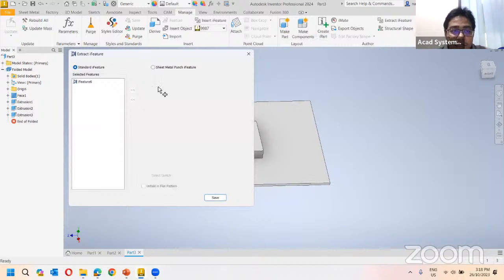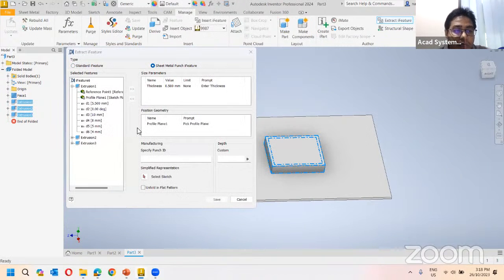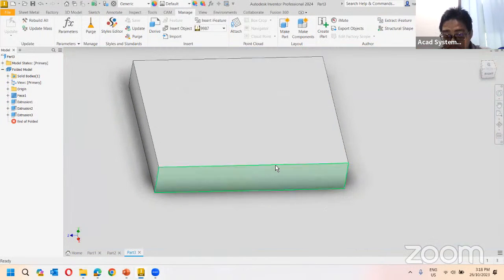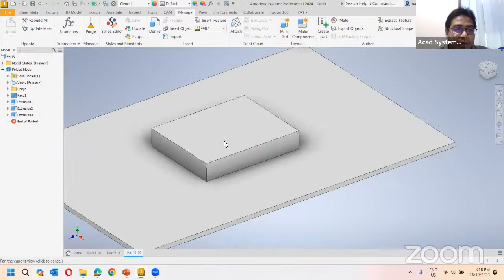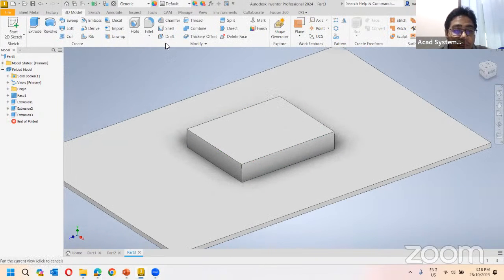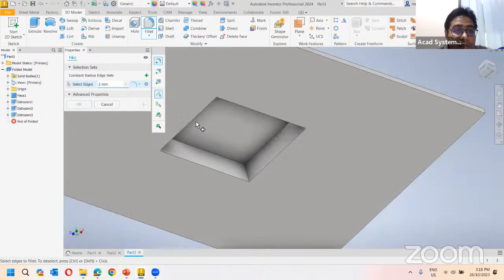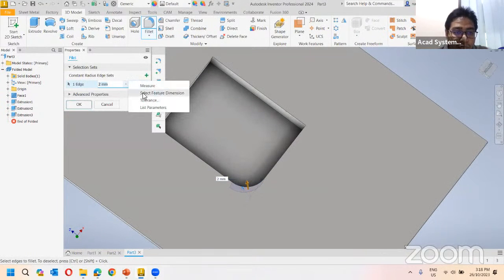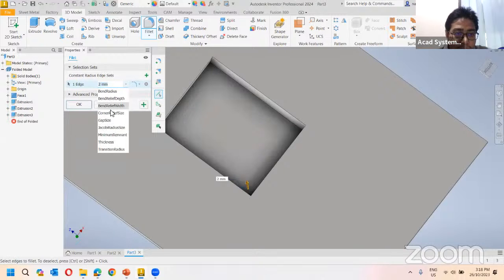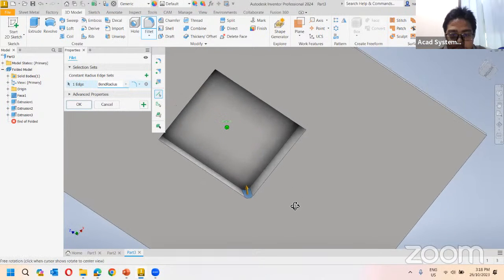Now, if I extract this into sheet metal, it will look exactly like this in the punch tool. But of course, it's not realistic because usually we have a bend, so I'm just going to add some more features to make it look like an actual punch tool. Fillets here will follow the bend, so I'm going to use the bend radius.